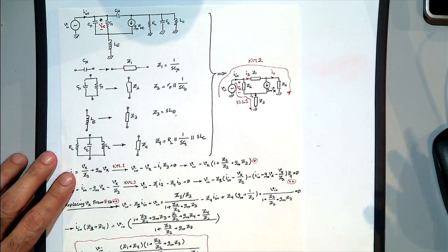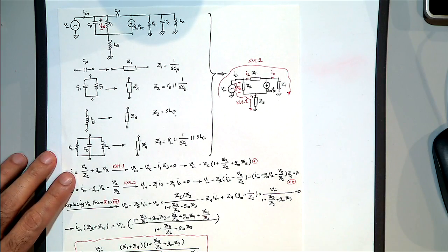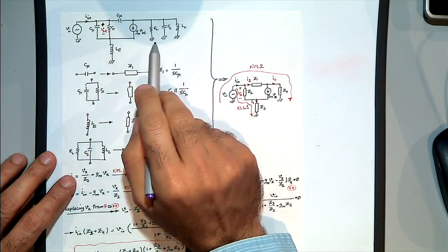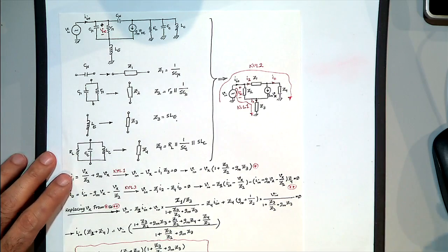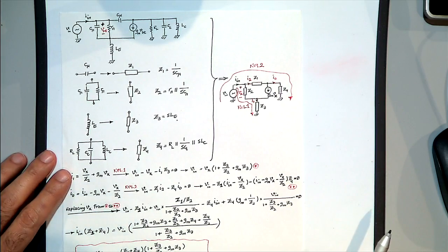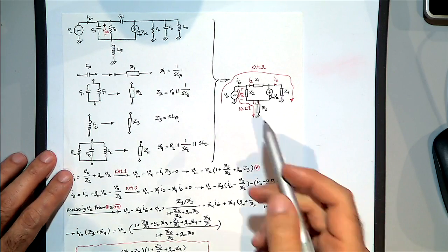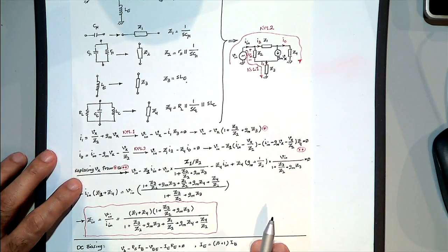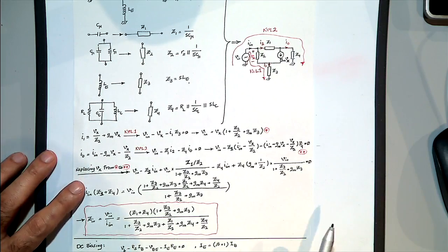So this is another thing that we can consider. In IC design, for example, we usually don't have any R in the chip. All the R are manufactured and fabricated by transistors. When you are looking into the emitter of a transistor, the impedance is 1 over Gm.